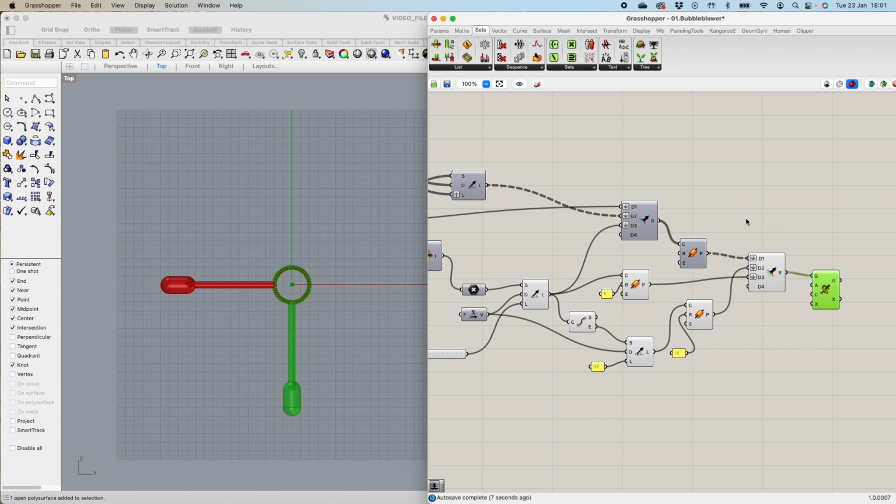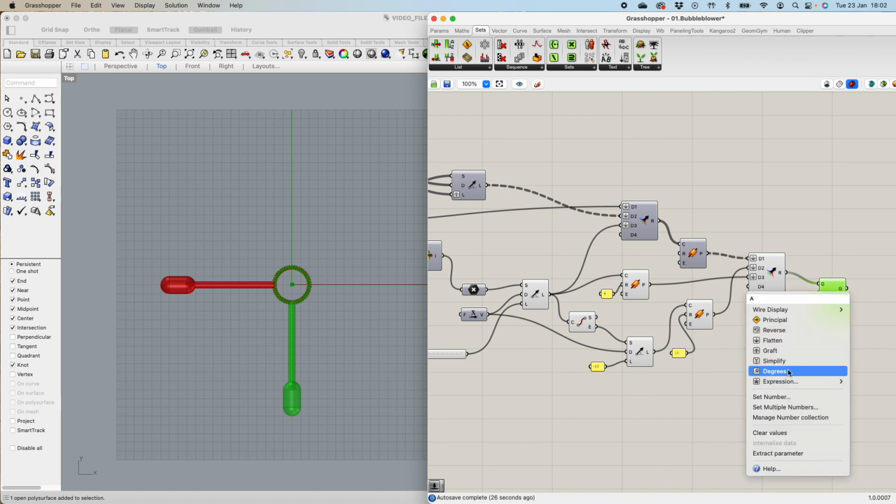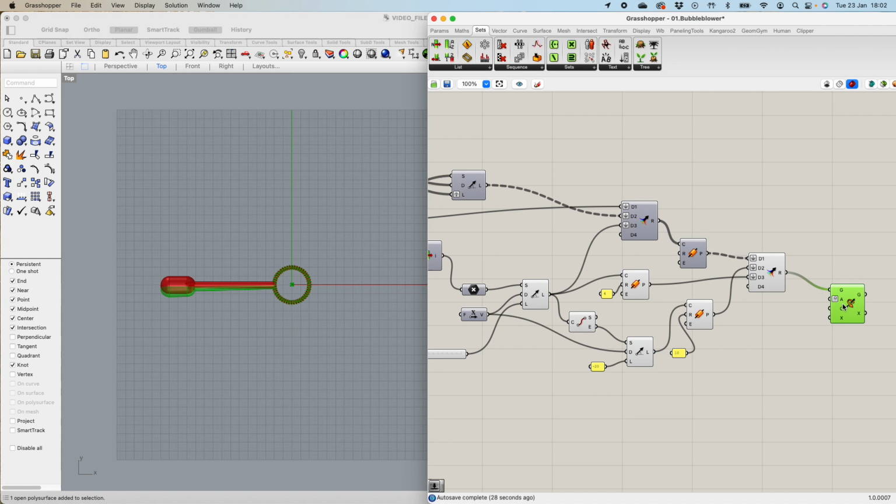This is an angle, but this does the job already. The center is at the X and Y, and the axis is Z, so it rotates around the Z axis. Let's do that. I switch it over to degrees, panel 90. Right?